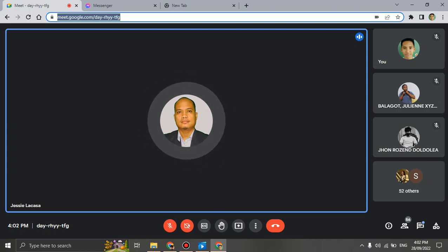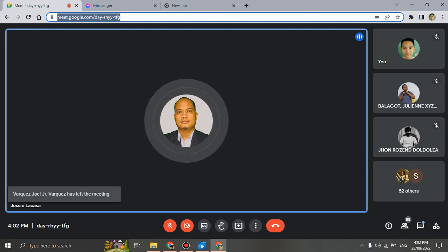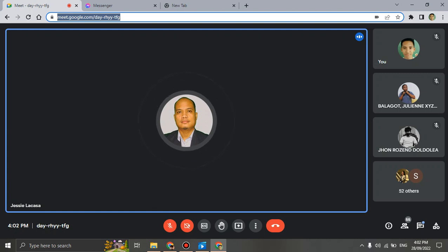So the figure below illustrates what actually happens when these supplementary loads are considered in plotting the room sensible heat factor and the grand sensible heat factor. On this psychrometric chart, it depends on the arrangement mode of your fan, where it is located, whether it is blow through or draw through.